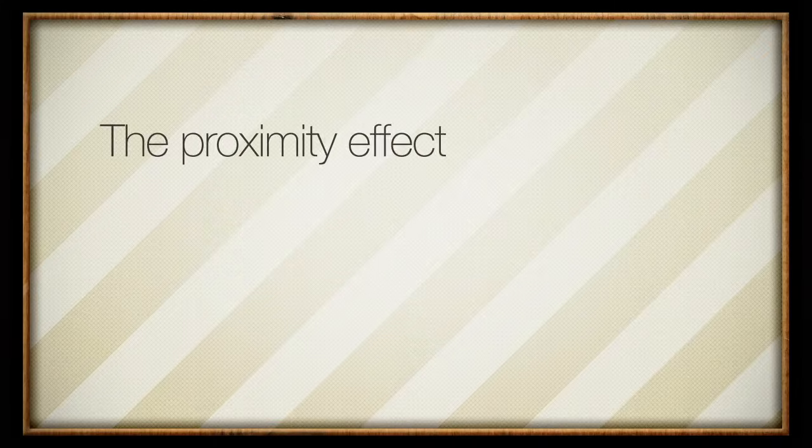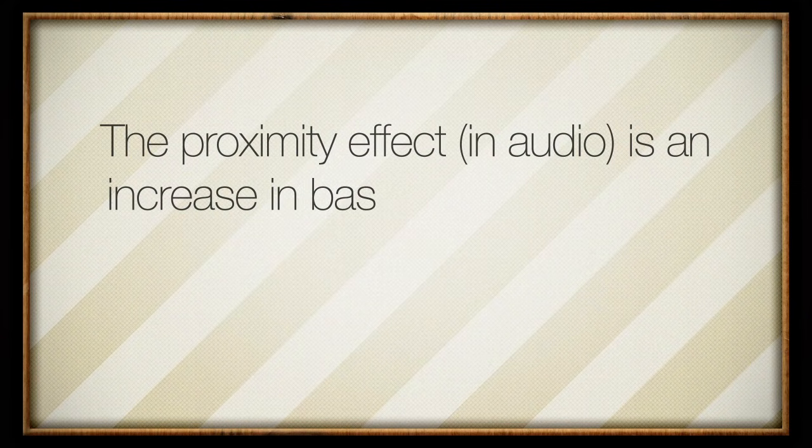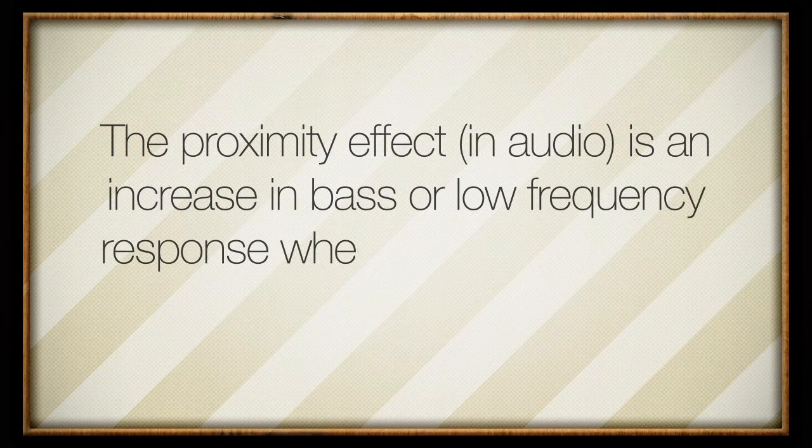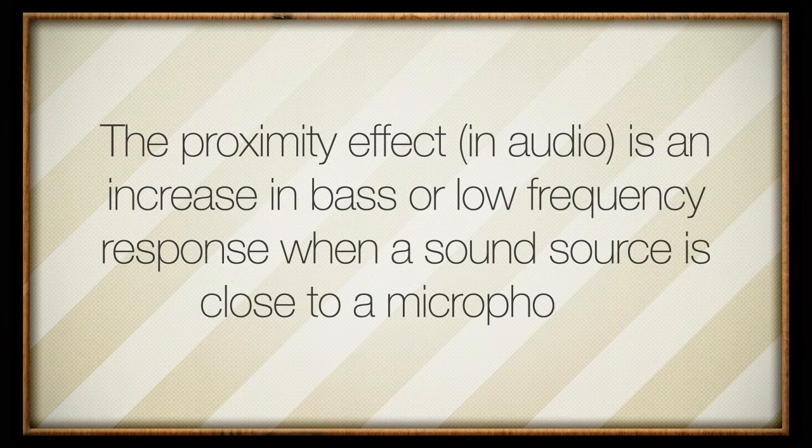Knowing about the polar pattern in a microphone is important because it will help you decide if the microphone is appropriate for what you are trying to record. Directionality in a microphone can be a good way to focus in on the sound source, but directionality also causes proximity effect. The proximity effect in audio is an increase in bass or low frequency response when a sound source is close to a microphone.